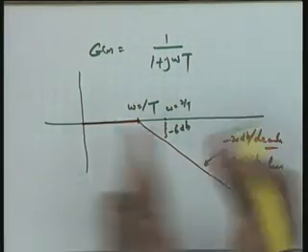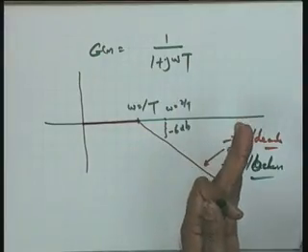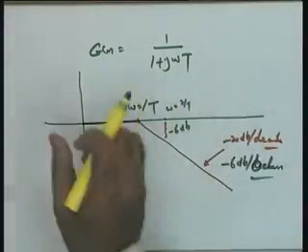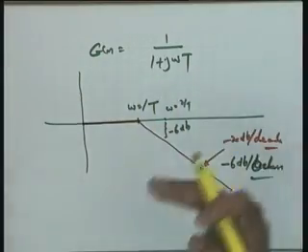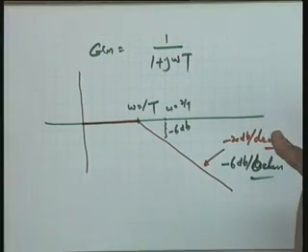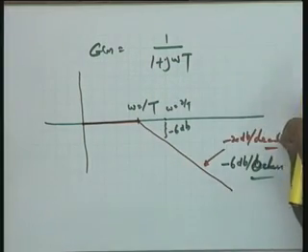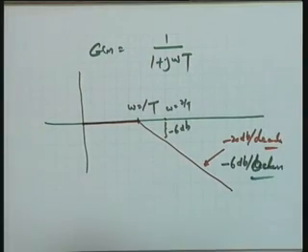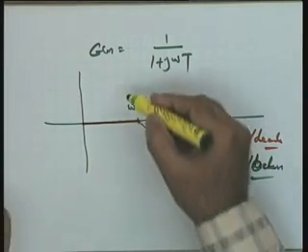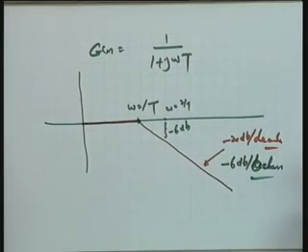This may be helpful in case the graph paper is not available for a decade. One octave on the other side also you can take to make a line of minus 20 dBs per decade. Minus 6 dBs per octave and minus 20 dBs per decade are identical, they are the same. So you see that this is your corner frequency, and this is called the asymptotic Bode plot, please.